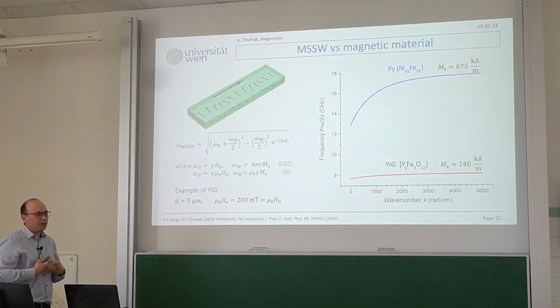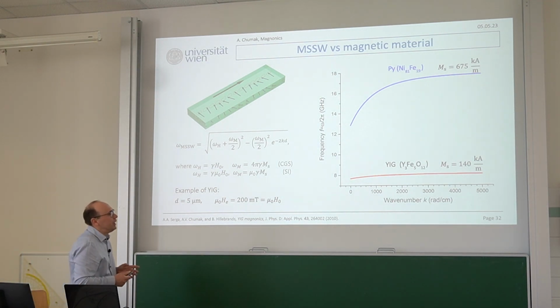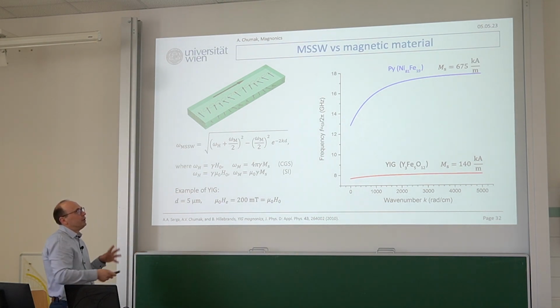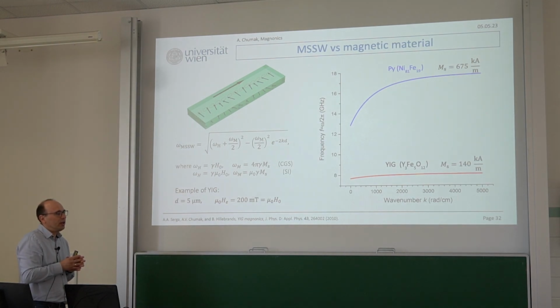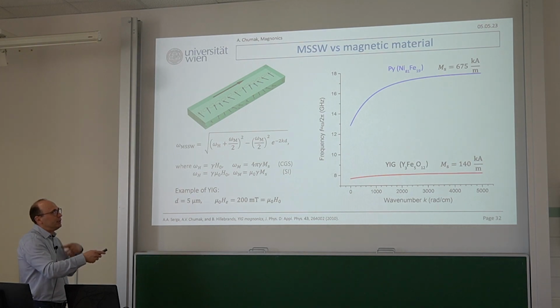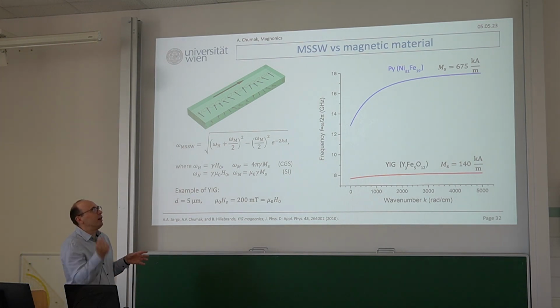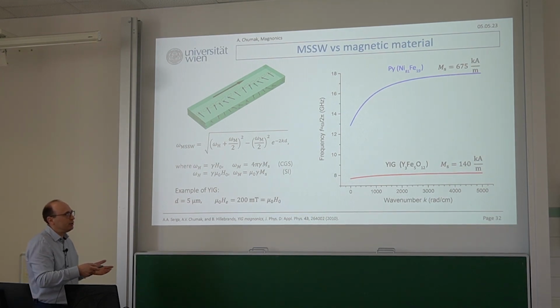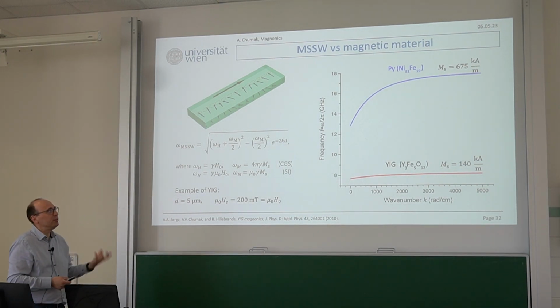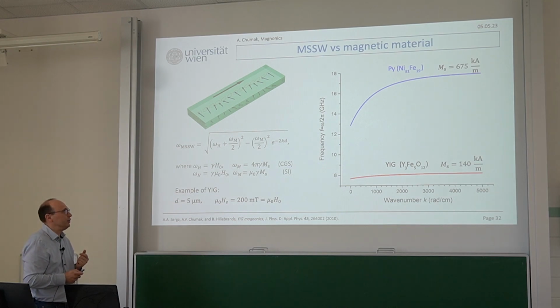Of course, in reality, you also need to take anisotropy into account, for example, hexaferrites. It's a material where M is not so big, but there is a big induced anisotropy, like in barium hexaferrites. Then you can define a so-called M effective, where the anisotropy is included, and then you can go to 60 gigahertz simply by changing material and still applying a small field. If you want to work with YIG at 60 gigahertz, you need to apply a very big field. That is also possible, but you need to think about where to get such a large field for YIG.